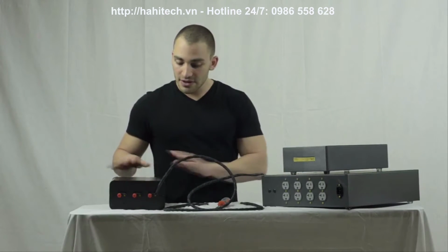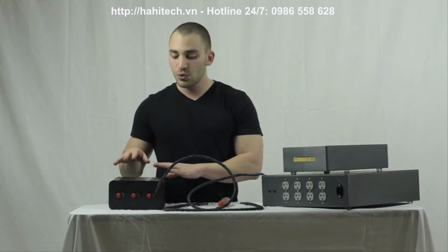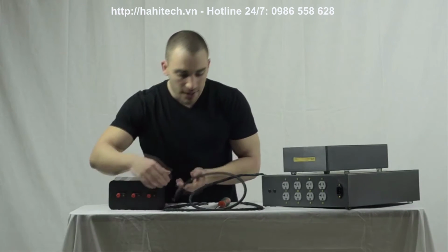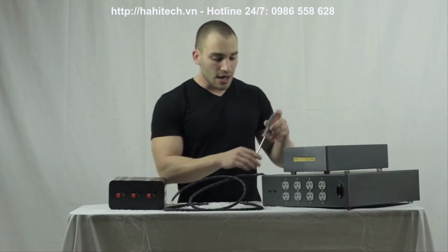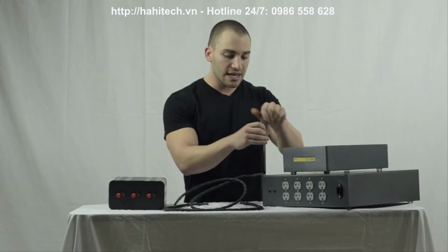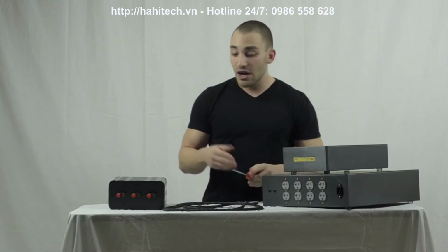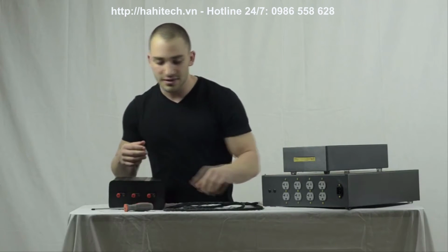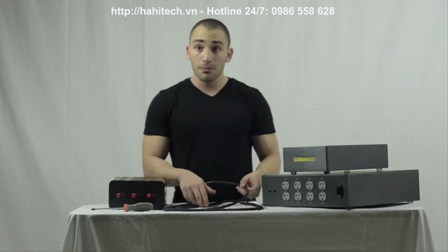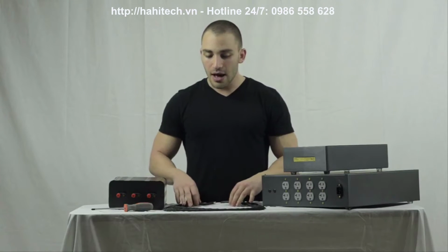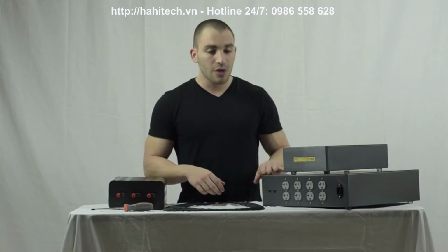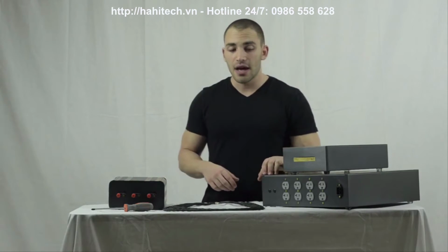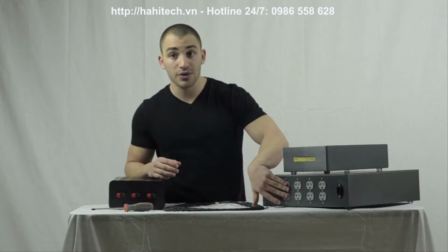The other tweak, obviously if you don't have a Colossus, and in this tweak I'll give the disclaimer that sometimes it works, sometimes it makes the problem way worse, just from the standpoint that you're creating additional paths to ground that aren't necessarily lower impedance. But one thing you can try at home that can be of a huge benefit is grounding all of your chassis in this way to a single power receptacle.